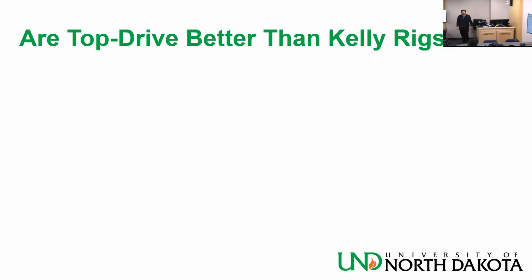Also, when you are drilling with the top drive, you drill faster. You can apply more weight on the bit, and it's more powerful. It's modern technology versus the Kelly rig. There are small Kelly rigs in Texas from 1969 still operating.